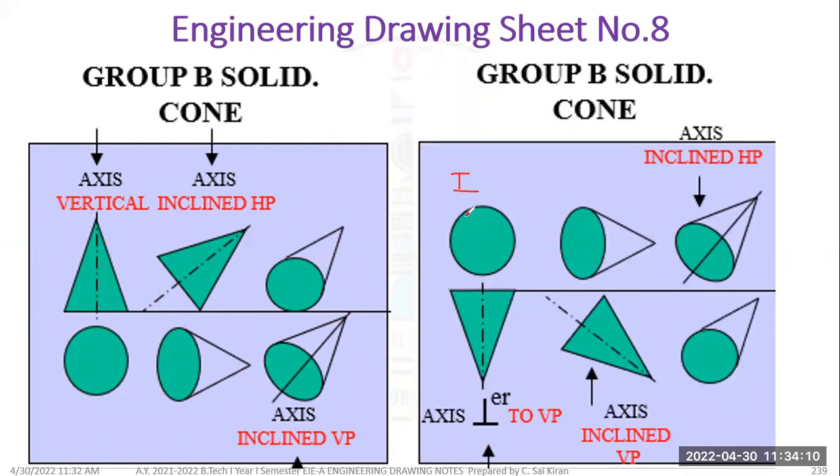This is my first stage. You have to draw the circle first, then make the projection, and give the axis height. This is my stage 2, and stage 2 and stage 3 have the same dimension, just rotating at an angle of phi and making the projections.